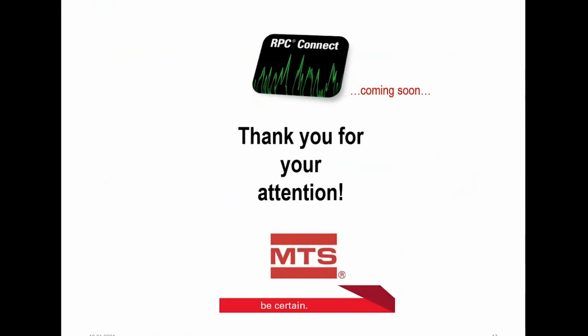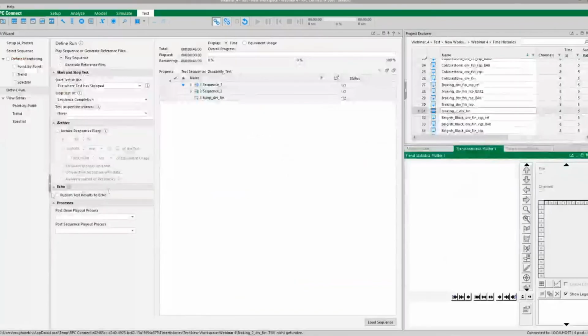Here's one. Is it possible to send the overall progress test status to the Echo software? Yeah, so that is possible. If you go here to the Echo section and click on Publish the test results to Echo, this overall progress, depending on what you select in the Echo software, of course, will be shown. So this is possible if you have a main window where all the rigs are connected, and you want to see on one window the overall progress from each test run. Of course, that is possible now in RPC Connect.